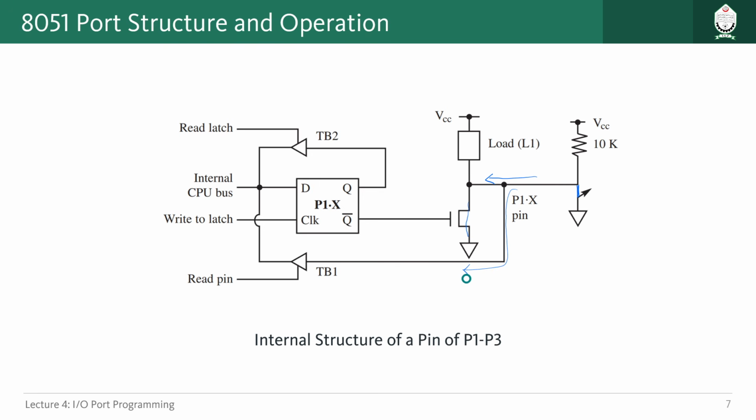And for the situation when this switch is opened, we are directly going to get this 5 volt through this resistor that will come here. So obviously there will be some amount of voltage drop here, there will be some current flow here, but because of this resistor, at least this MOSFET will not get damaged. So we can avoid that mishap using these resistors.